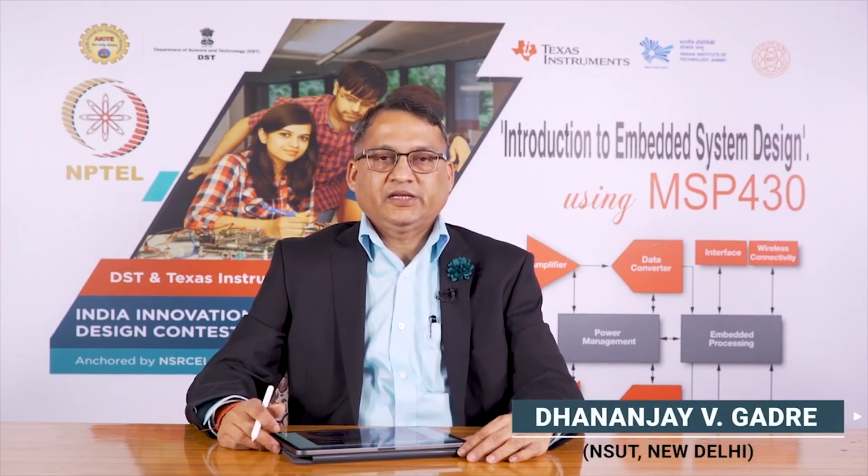In the last lecture we covered some ground to understand the components of a single purpose computer, namely we need a sequencer and we need a data path. The sequencer is nothing but a finite state machine. That finite state machine could be implemented either as a Moore machine or a Mealy type of finite state machine. It does not matter. The data path elements will be determined by the requirements of this single purpose computer.